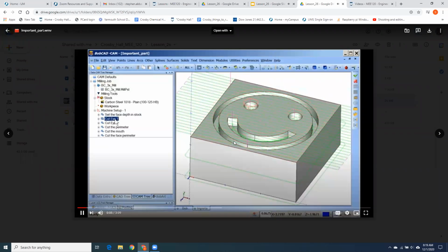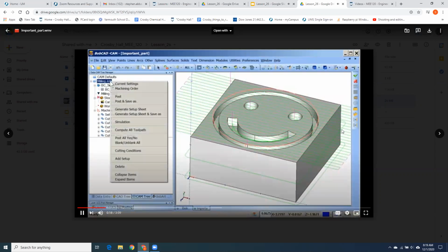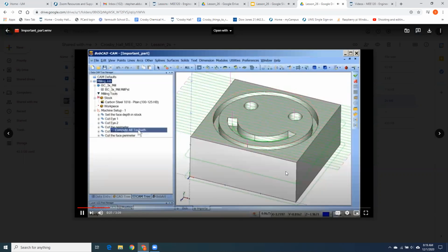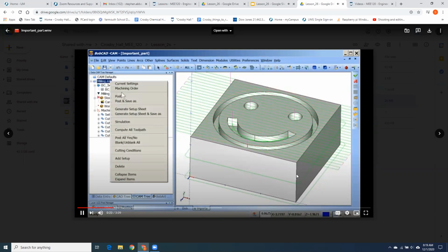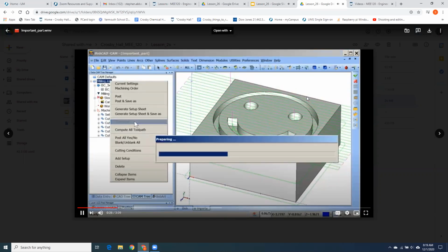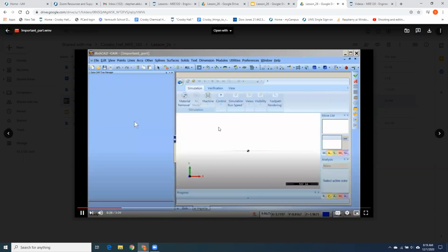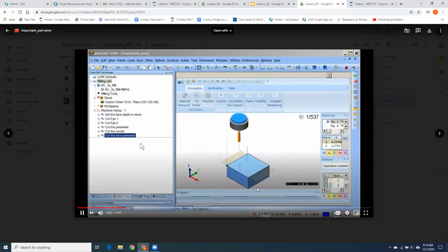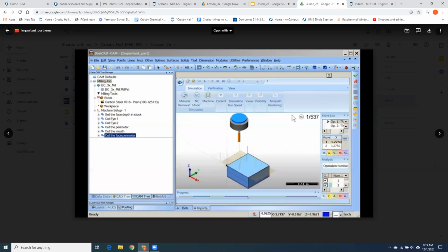So in this important part, what I want you to get out of this video, see how I've created these square corners in the mouth of the happy face? Okay, I'm going to take that rotary tool and I'm going to program this SolidWorks part to try and actually create it in metal, as you're seeing here. So what happens is you come down, you face it off, just like this. So now I know that I've got a flat piece of metal.